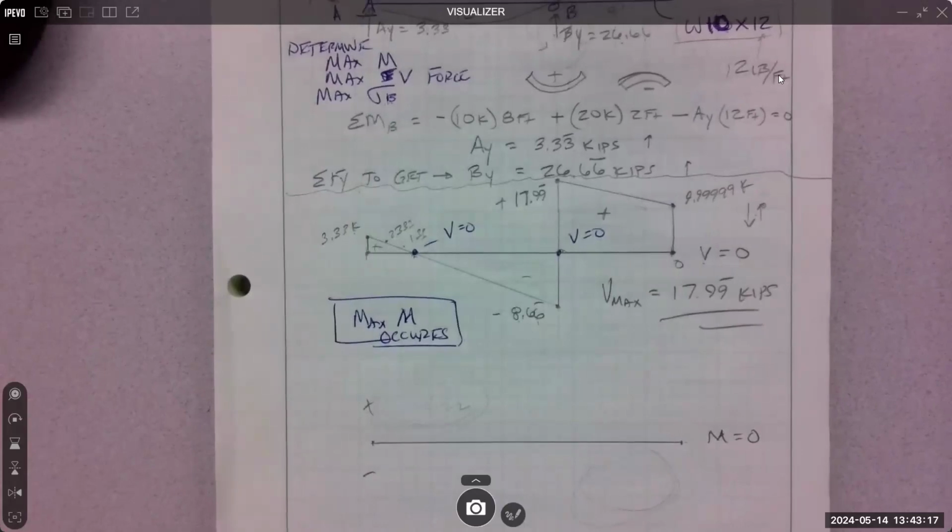If you can see, like, if it was a simple beam with two supports and a bunch of load down, then you know the moment's all positive. Like the entire graph would be positive, right? As things get more complicated, we can't go completely by that rule, it's just something to think about. All right. We build the moment graph from the shear diagram.